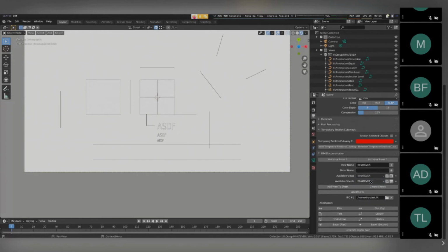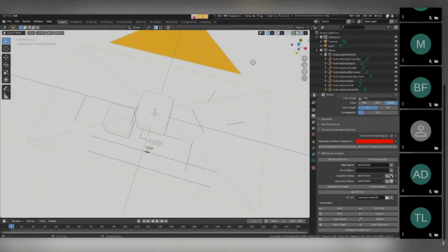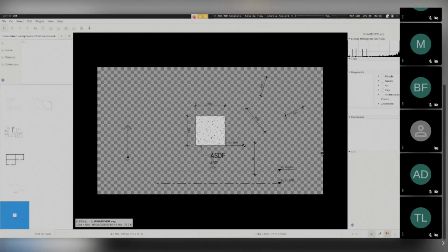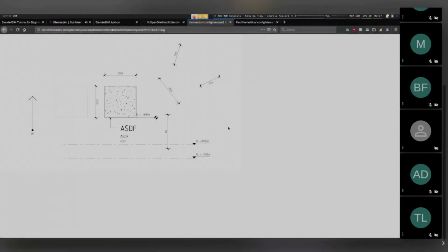By the way, if you have set up your default SVG program, you can press these buttons as well. Pressing this button will take you to the view like that. So I can drop down to my view and press the button. Pressing this button will open that view in your default SVG program. I haven't set that up on my computer, so it doesn't work on my computer, but on other computers where you do have it set up, it should work. If I press that, I will get this image editing program, which doesn't view SVGs quite so correctly, but on your computer, it should work better. That way you don't need to do what I did in Firefox and browse to it.